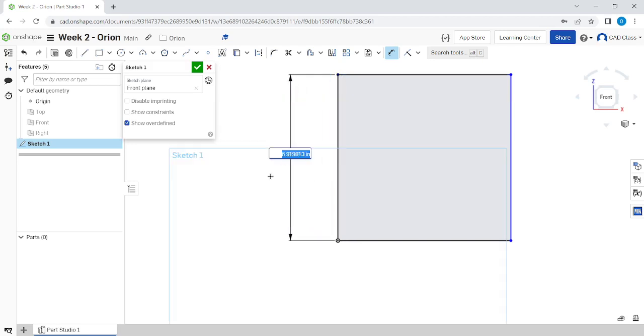So what you're going to do is click and place it again. And you'll notice this turns into a text box. I can edit this text in here. I can click and select, and I can backspace, and I can edit. So let's type something in here. If I type a number 2, this will default to inches. So this is 2 inches. I can also type IN for inches. I could also type mm for millimeters or a single m for meters, and you'll get some of these little tool tips showing up that show that you're using supported units. I can also type in feet, whatever you want to do, but type in 2 inches, or if it's your default unit, just type in the number. And then you're going to press enter.